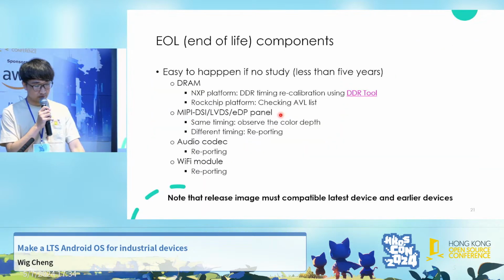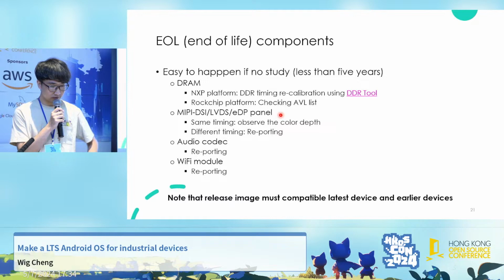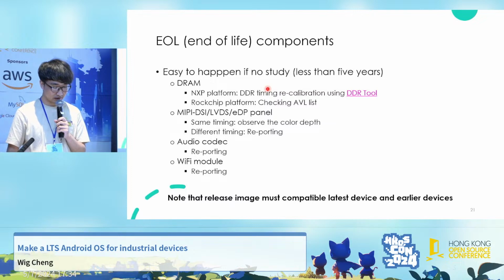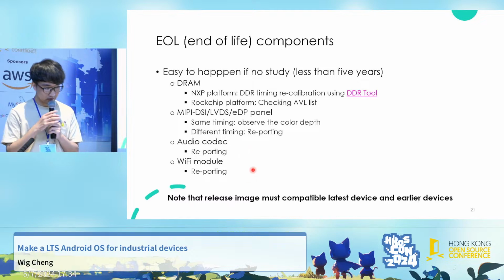Okay, I would like to talk about another question, about EOL components. EOL means end of life. It's easy to happen if you do no study when kicking off a new project. You will face this problem in less than 5 years. And I list the common hardware components which usually go EOL: DRAM, different interface panels, audio codec, and Wi-Fi module.